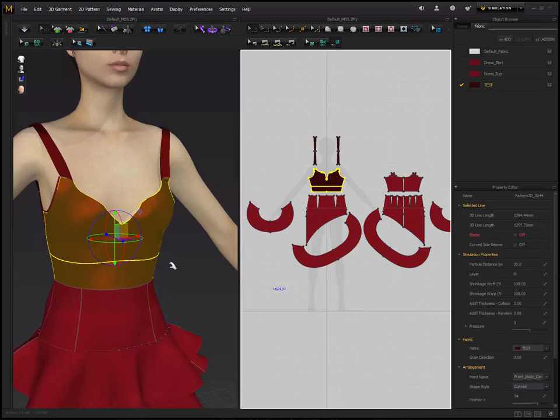Layering is the option to put layers on top of other layers and to say this hoodie is on top of this shirt and don't fight with it, don't have the shirt on top. So you could change it temporarily, say this hoodie is layer 1 and the shirt is layer 0 and the hoodie will be simulated on top of the shirt. Shrinkage, weft and warp, you don't have to worry about. This is the fabric. Stretching, weft is the horizontal and warp is the vertical. You don't have to worry about that. Leave those as default.